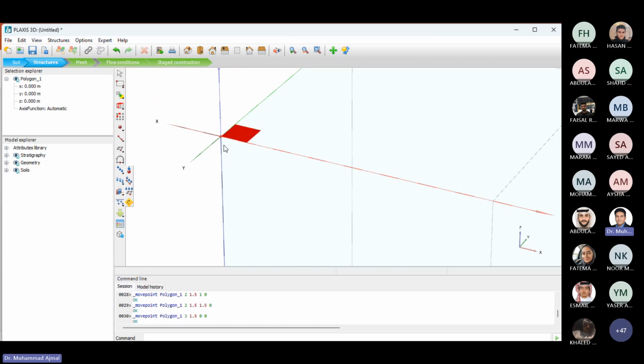Another approach is that you apply a displacement in this surface. If you remember from your structure analysis, either I can apply a force to get displacement, or I can apply displacement to get forces. Now, displacement control analysis is much more controlled than the force based analysis.